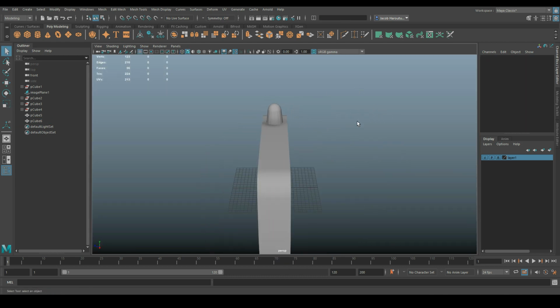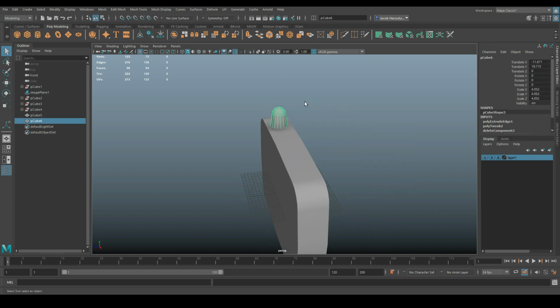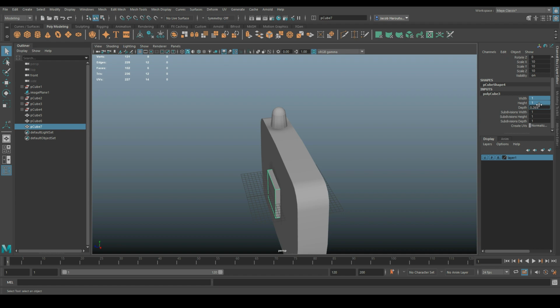And what I realize is that it's not a perfect circle, so I'm gonna go ahead and use my calipers and get the measurements of the thickness really quick. And the topmost part of it measures out to be 0.265 inches. And to get 0.265 inches, I'm gonna create another cube, multiply that by 10, and do 0.265 inches.